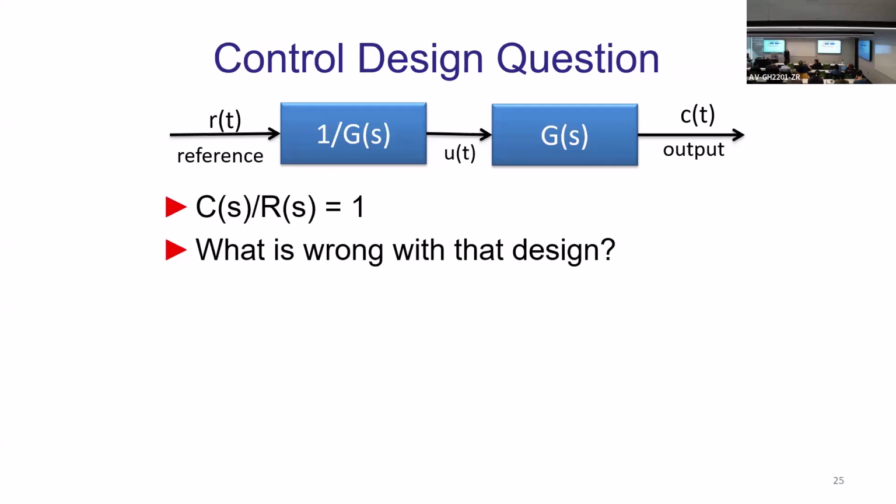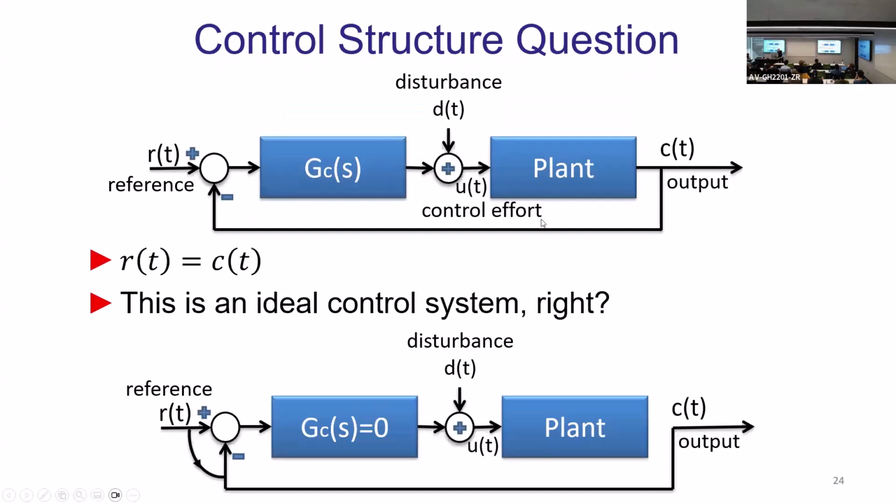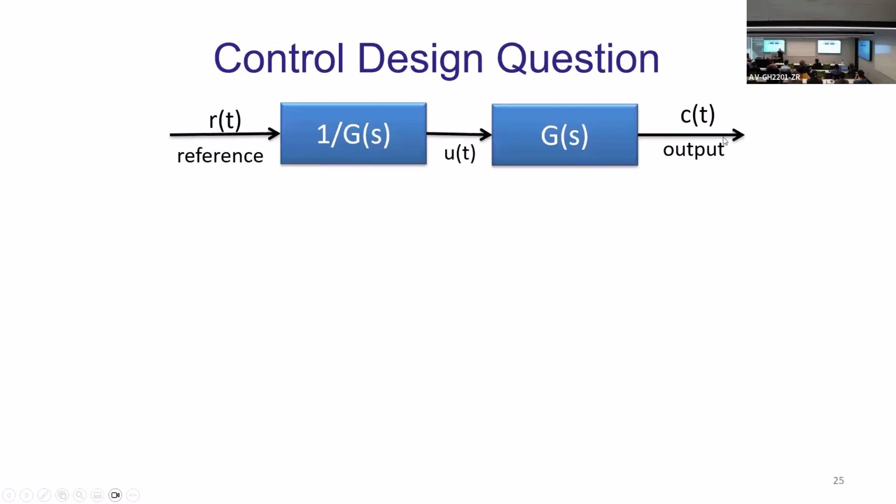What is the difference between this system and the system in the last slide? In the last slide, the motor got zero input. There was no input. This is 0 here, 0 here, 0 here, 0 here. Nothing coming to the plant at all, and I'm not even measuring the output of the plant. In this one, I'm measuring the output of the plant, which is the actual number of rotations per minute, and I'm giving it some input, whatever that function produces, let's say a step response. It computes the output voltage, gives it to the motor, and the motor starts to rotate somehow.